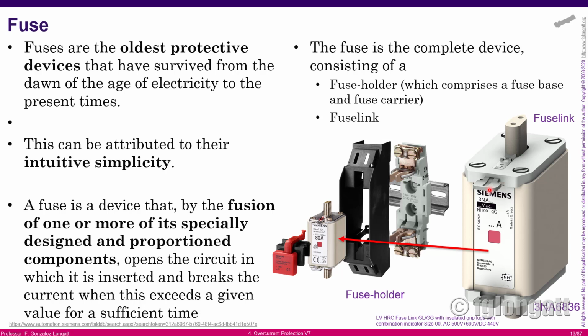That is brilliant. There is a reason I say to my students, the power system has been smart for a century, because electrical engineers working at the very early stages of power utilities were extremely clever. They used very basic physics in order to make the power system work. The fuse is one of the technological examples: something extremely simple, a conductor that fuses when the current is above a limit. That is extremely clever and just basic physics. You don't need internet, you don't need ICT.